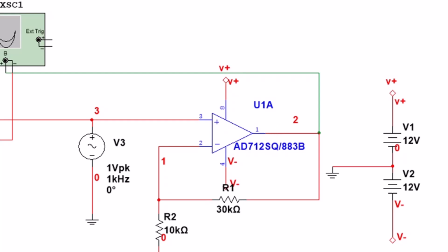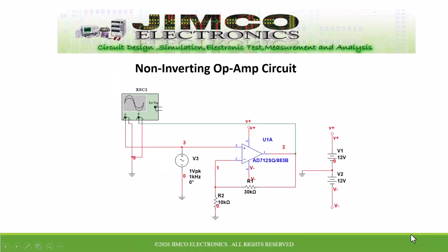The typical op-amp amplifier comes with two DC supply voltages, one positive and the other negative. Usually these DC voltages are left off the schematic for simplicity, but they are always understood to be there.